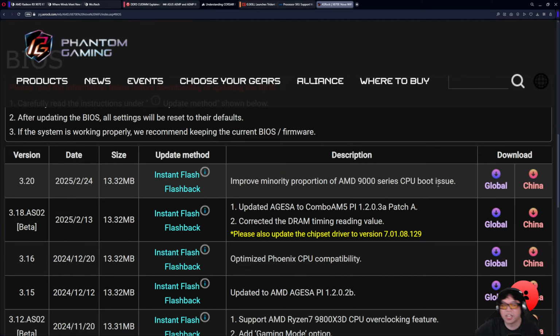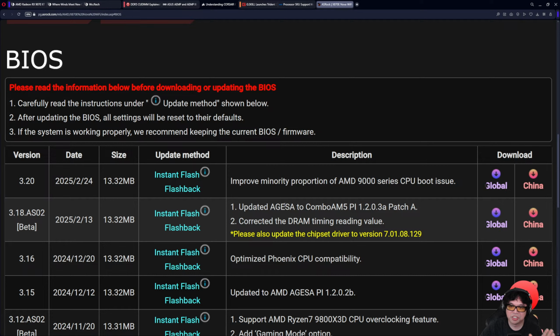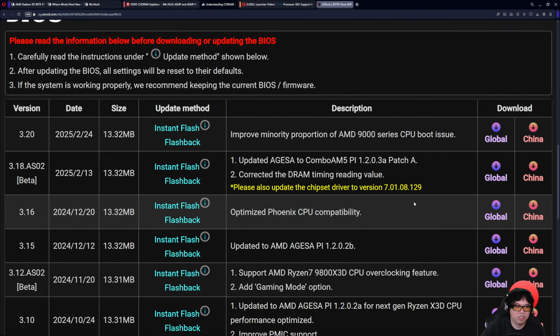So that was the only actual problem. And let me be clear, this doesn't kill a CPU. If the voltage is not high enough, it doesn't kill the CPU. It just makes it so the CPU is not stable. So you have to raise the voltage to make it stable. So that is the answer on the quote-unquote ASRock motherboard issue. That is literally the root cause of the issue. It has nothing to do with ASRock's motherboards killing CPUs. That was not happening. The few reported instances of that happening were down to user error.